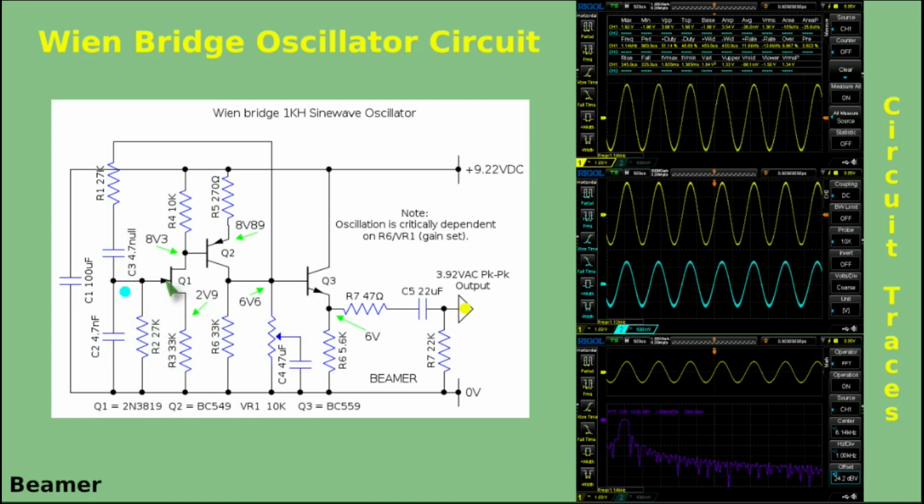Moving on to the JFET, we are in a drain following configuration, and this represents fairly little gain in itself. The voltage gain is all in this transistor circuit here. And by the way, because you're coming out at the drain, there is a 180-degree phase shift between the gate and the drain. And as well as a voltage gain circuit here, this is also 180 degrees out of phase between the base and the collector of this